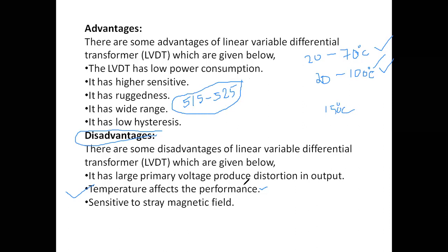So these control valves are mounted, or these LVDTs are mounted on these pipelines, which will take this much temperature. So there are some temperature effects also, right? And the most important thing is it's sensitive to stray magnetic fields. Okay, so these are the disadvantages while using these LVDTs.